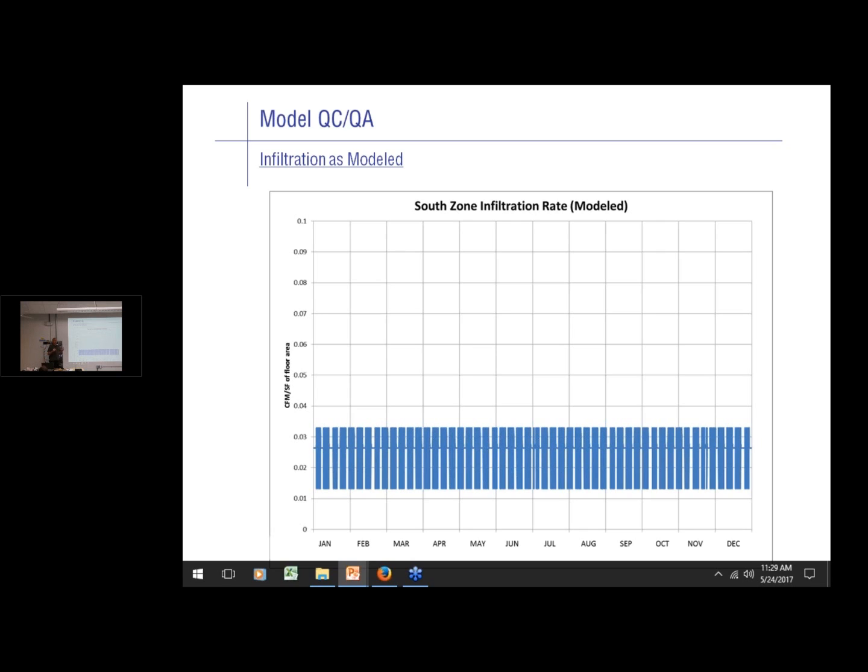So understanding how much total CFM, or in this case CFM per square foot of floor area, is actually moving through your zone and through your building, there's no easy report to find that. That can be a meaningful number. If you just check your fan operating hours on a lot of models right out of the box, what you'll find is that the fan is cycling on an excessive number of hours at night.